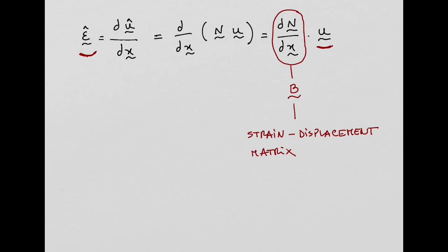And basically, this B matrix is the derivatives of the shape functions, which, as you have seen in previous sessions when we did some examples for beam deflection, we built the shape functions from polynomials, right? And the derivatives of those polynomials in order to x in that case, because it was only a one dimension example, it was quite easy to do, right? We had derivatives of x squared, x cubed, so quite easy to do. So in this case, the shape functions are defined depending on the finite elements you are using on your mesh, and the analysis you are doing.